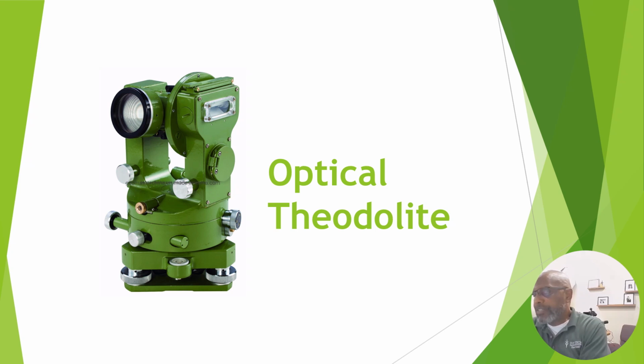This is a very rapid system for turning angles and is an excellent construction site instrument. The typical scale reading theodolite is a glass circle with a simple scale that is used to read it. Simply read the degree that shows up in the window and observe where the degree index mark intersects the scale.